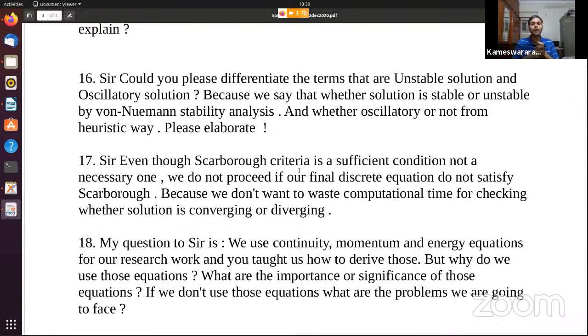Now, the von Neumann stability analysis is more formal. If it says that the scheme is unconditionally stable, you can still get an oscillatory solution, but the solution will be bounded. It will not blow up to NaNs or something like that. Now, stability, of course, does not mean that it is correct or accurate.